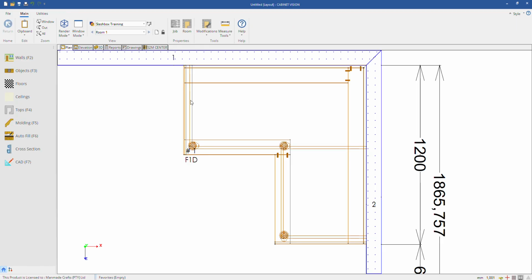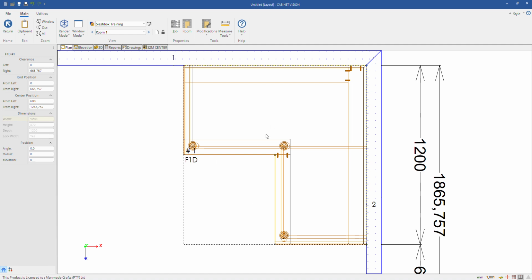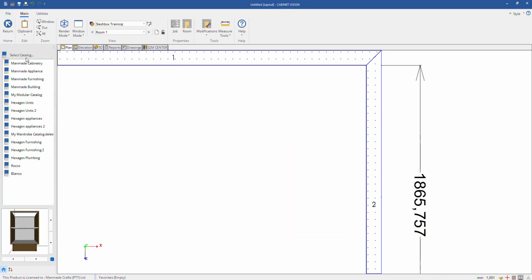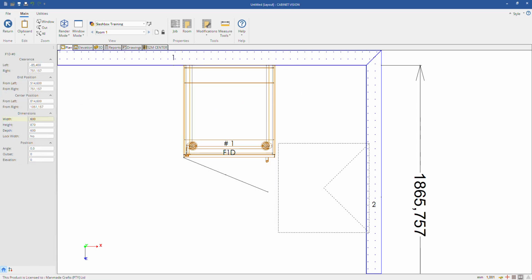Now with this corner unit, I cannot change just this piece's length specifically or this one's length specifically, because it is now a solid set unit. If I go and change anything there, it will not allow me. It's locked on those sizes. To get those specifications correct, you need to specify the unit sizes first.